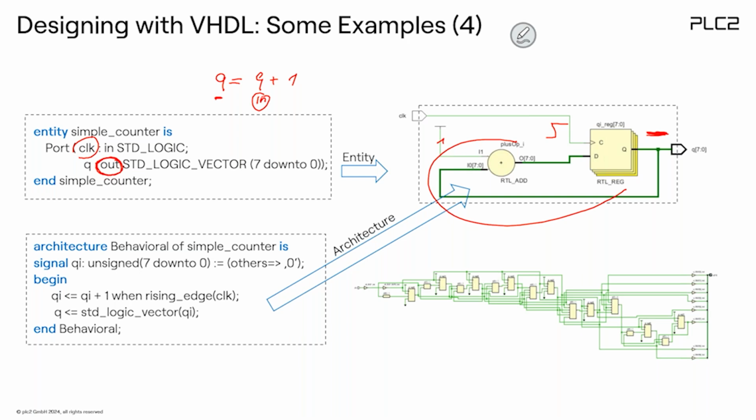So again, this was what I talked about. Actually, we would need a buffer, but I don't like to use the buffer. So now the very simple workaround. Whenever you do this, you need maybe an internal signal which is used again for something. What you do first, you define an internal signal in the declaration area, maybe call it QI.